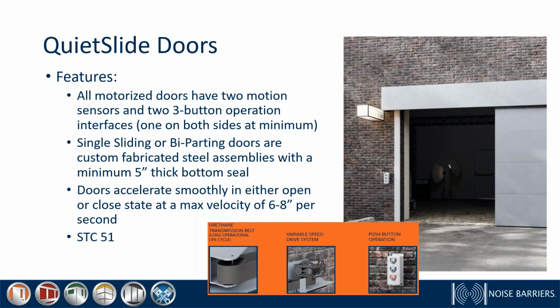A couple of things where most of these motorized doors, a lot of the other vendors provide these in broken down components. For the most part, these doors come almost fully assembled. The header rail system where the door hangs off of is fully tested and assembled in the factory with all the sensor positions. The only thing that's basically installed in the field is a couple of loose items, is your jambs, your headers, your baffles, and also your slabs. If you have a 10 by 20 door, you're going to have them in slabs of 3 to 4 feet in width, in height by the length of the door.